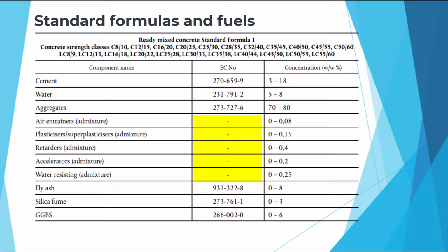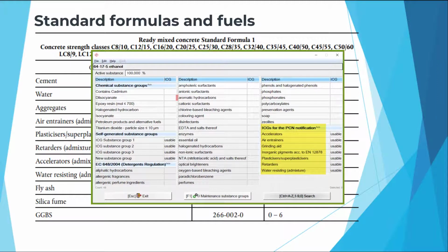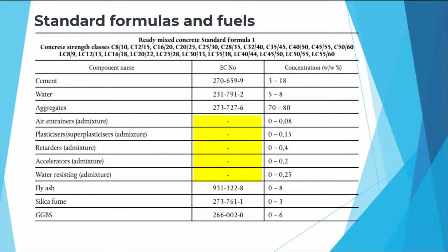A special situation is caused by standard formulations in which individual ingredients have not been identified by EC numbers. For this type of raw materials one has to assign substance groups. These special substance groups are already predefined. The input is identical to that described for the ICGs and is also possible for MiMs. You are not required to assign these substance groups to the raw materials, but if they are available, it will allow the program to make better suggestions for the assignment of standard formulations and also a more correct determination of the percentage ranges to be submitted to ECHA.